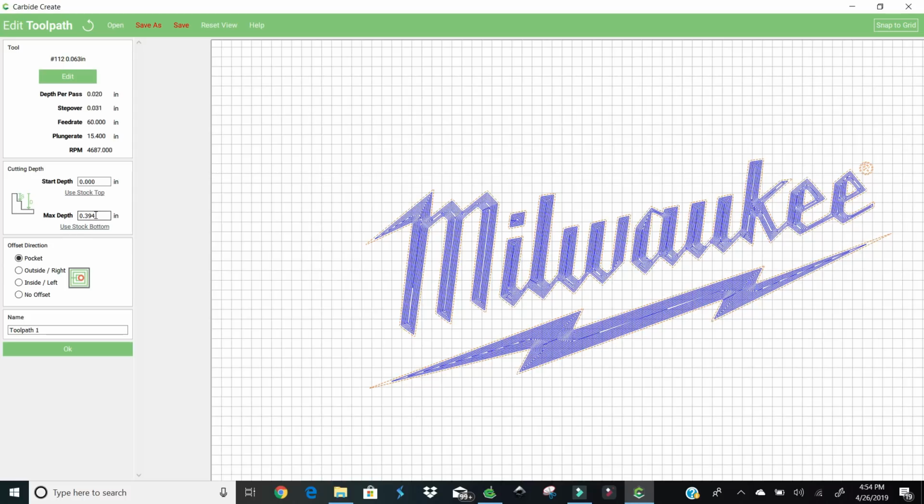And then the max depth, I don't need it that deep, right? I don't even want it maybe 1/4 of an inch. I'm going to go 0.150, right? Because I don't need it that deep. And I'm going to hit OK.